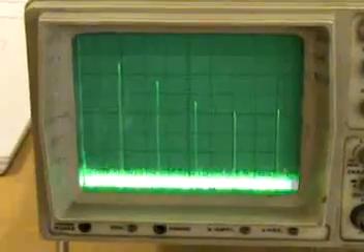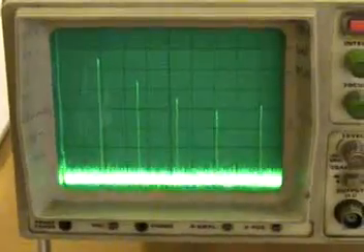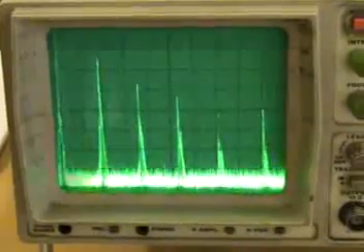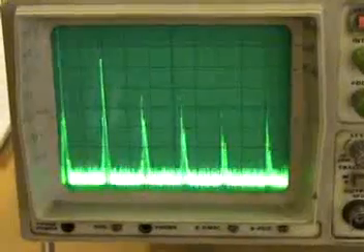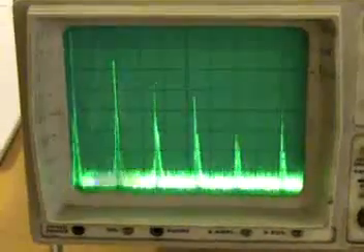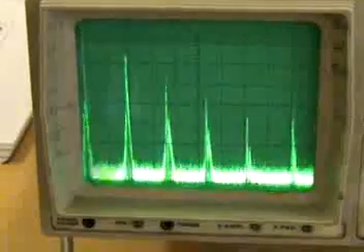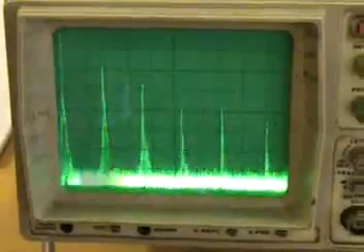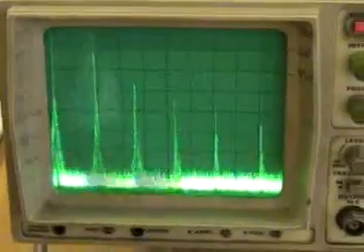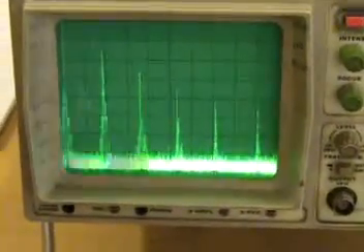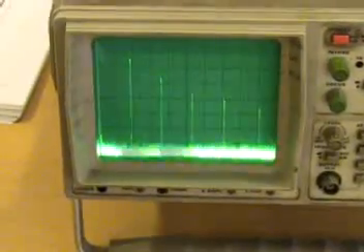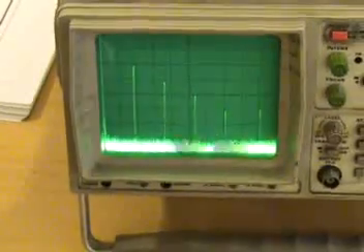If I reduce this supply voltage, I observe that the level of the harmonic goes down, while there is a voltage at which the oscillator shifts out of its frequency and stops functioning. This is because of the pushing characteristic. The tuned frequency of the resonant circuit has shifted from its crystal frequency, and that is why we see such waveforms. Now we see that the oscillator dies down.